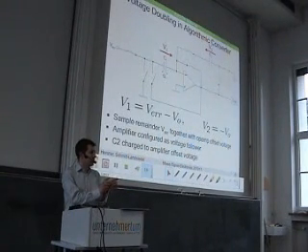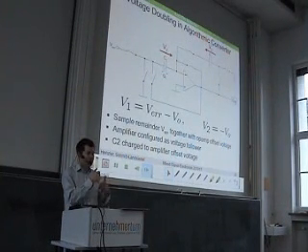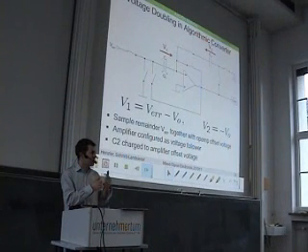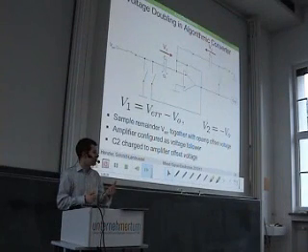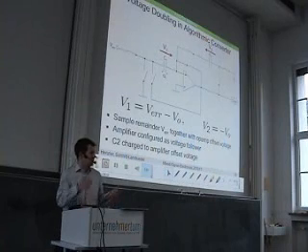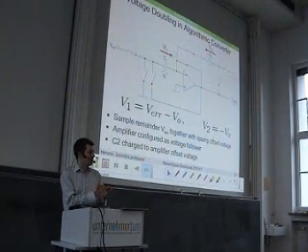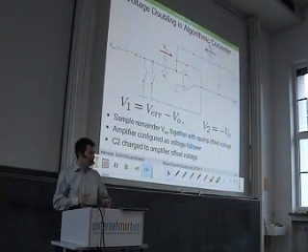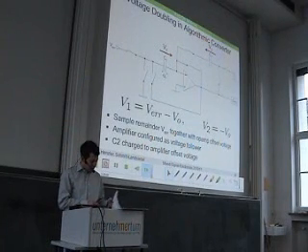So the factor of 2 is not by ratio of caps or by ratio of resistors or whatever, but the factor of 2 comes into play by sampling twice. And hence it is a very precise factor of 2. Because sample, sample again, combine. Then you have the charge 2 times, independent of any variation there. So go through this circuit. It's a very useful one to amplify the remainder by a factor of 2.